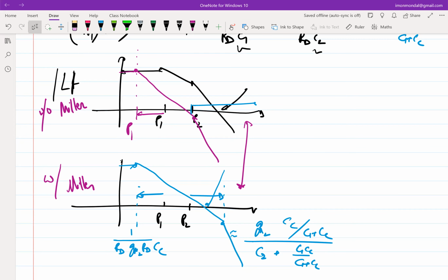That I can afford to move omega u loop to a higher frequency. Since P2 has moved to higher frequency, the excess phase is omega u loop over P2. If P2 has moved to higher frequency, I can afford to move omega u loop also to a higher frequency, which essentially means ultimately, even though we want circuits to be stable, we also want circuits to be fast. Having a higher UGB means my amplifier will work as an amplifier till higher frequency. So it is beneficial if any technique gives you a stable circuit, but with a higher omega u loop. So hence Miller way of compensating gives you a kind of a higher bandwidth.